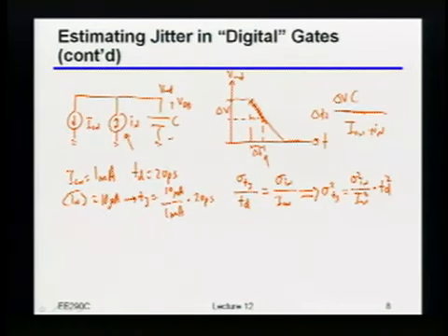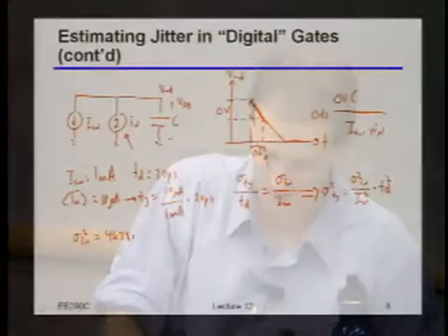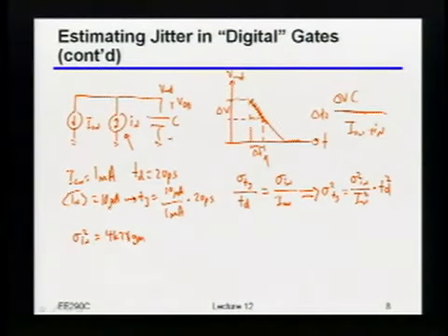So what is the variance of the noise current? What is that set by? In general, for a saturated transistor, what's that set by? 4kT gamma GM. It's 4kT gamma GM, but there's one more important thing you have to add there: the delta F. There's an alpha factor too, but let's even ignore that. There's a delta F here.